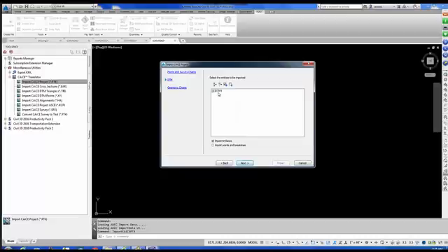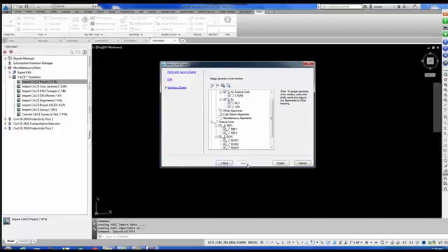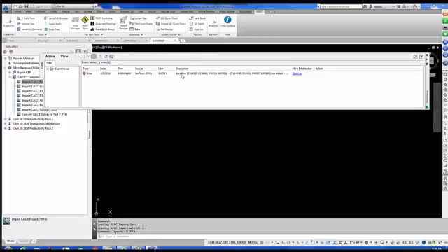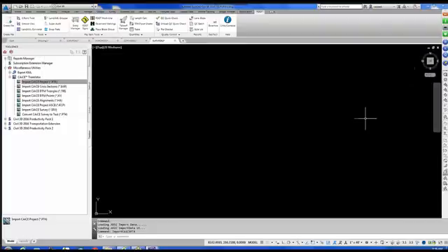Okay, DTM. This is my surface that it found in this CAiCE project file. How do I want to bring it in? I want to bring it in as points and break lines. Very similar to how we did it in the survey database. Right? Remember, we created a surface from break lines, and then we imported the points from the GDTMRD points group, and then we use that to create the surface from. Okay? Let's hit next. All right, now it also found some geometry chains. All right, those are your alignments. All right, I'm going to select all of those. You notice that the next button is grayed out. So when we hit import, it's going to import the points first. Okay. And it found there was a break line issue because a break line crossed another one. We can fix that.